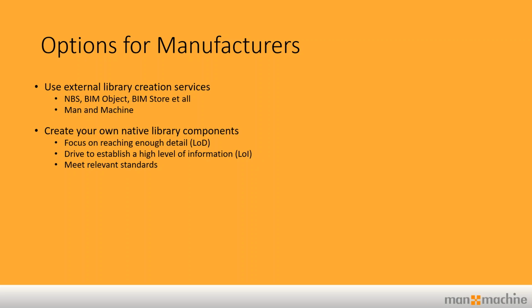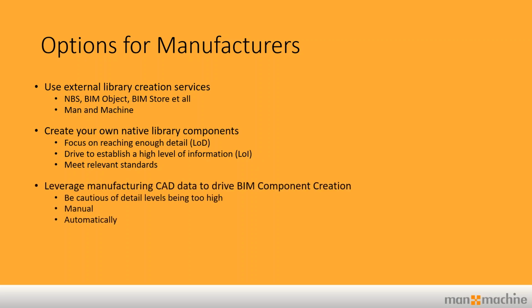Most people will aim for LOD4 as a maximum when they're creating BIM objects. We don't need to go higher than that. We simplify hugely. We shrink wrap inside of Inventor. We make sure that holes are covered and may be represented by 2D geometry only if they are vitally important to the design of that object. We will cover that shortly, live in technology.